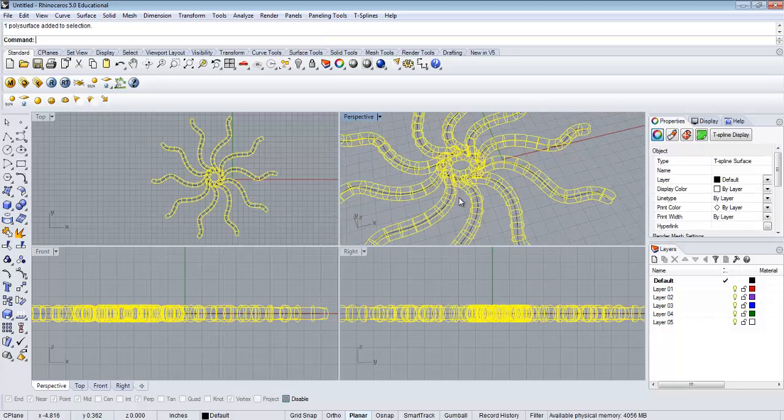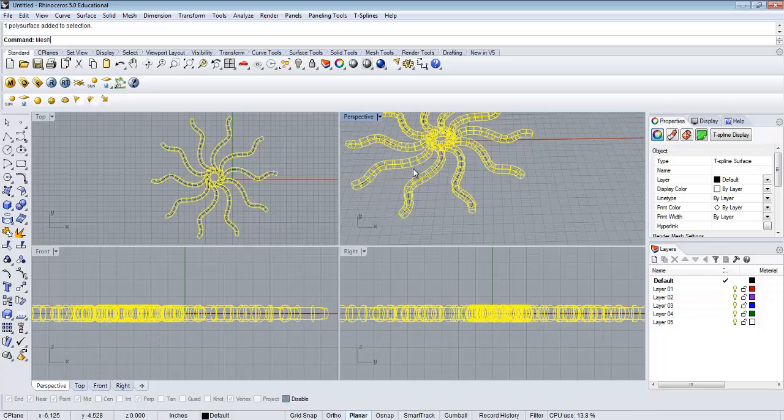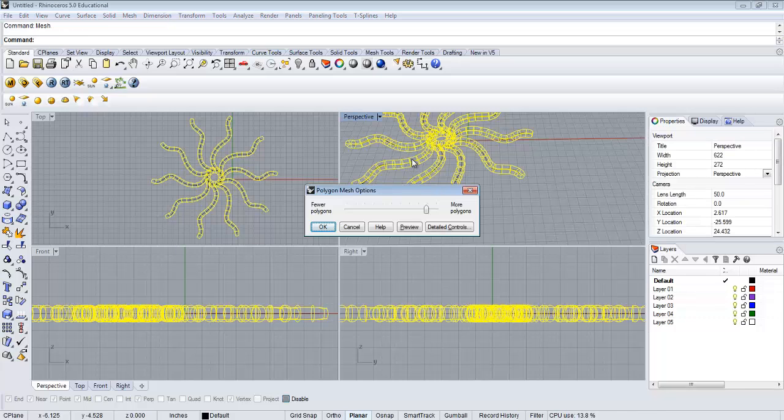This is one surface, and then we just mesh that because we need to basically enable the machine to talk to the printer. Rhino is a NURBS modeler, non-uniform rational B-splines, which basically means that it's based on mathematics, and which means that there is not really any granularity to that. And so we turn this into a polygonalized mesh that gives us very specific coordinates, and it makes things really ideal for talking to machines that have to fabricate things with real coordinate values.